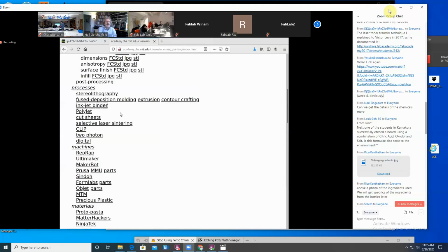This was Z Corp, spun off by MIT, bought by then 3D Systems. This is where you print an ink, and you use it to fuse a powder. The strength of that one is you can print at printing resolution, and you can print in color. The weakness is it makes weakly bound powder, and so it has poor structural properties. You later need to infuse it to strengthen it.